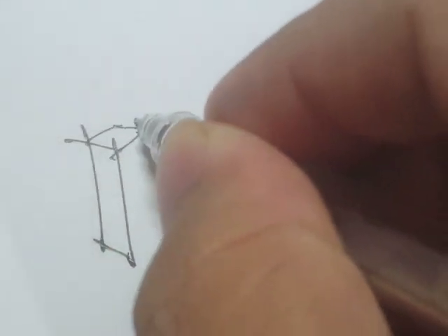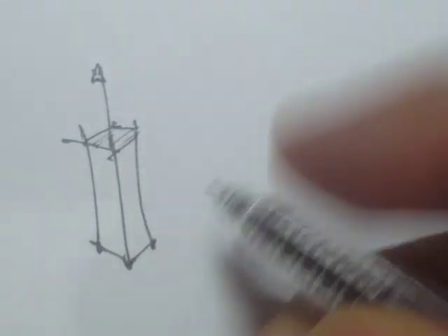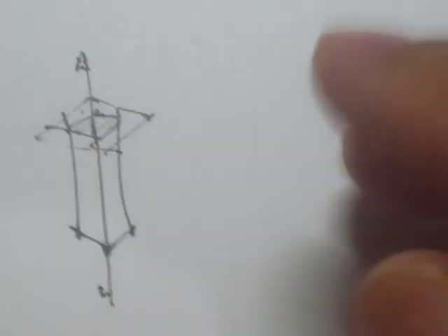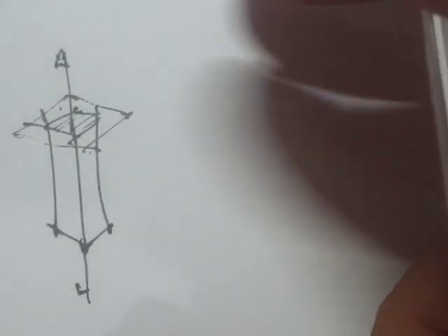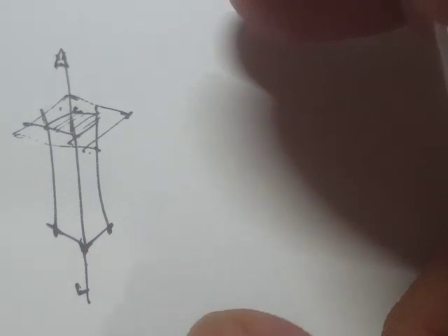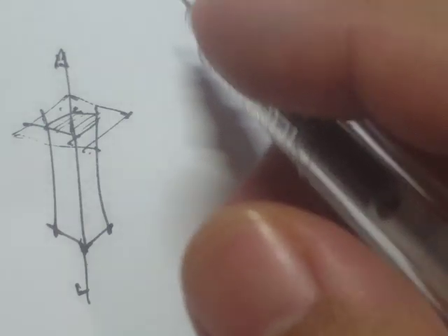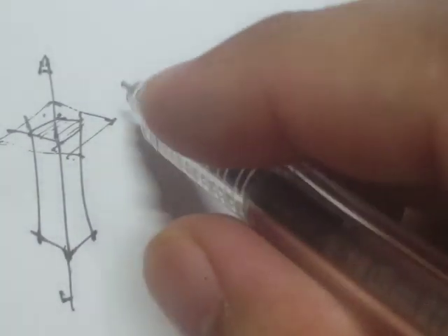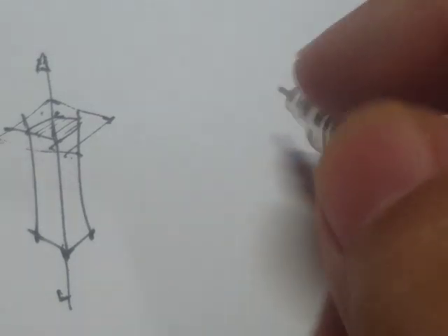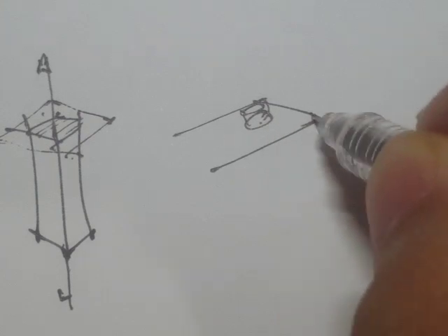Axial loading is a loading that's perpendicular to the cross-sectional area concerned. Typical examples of axial members are columns, struts, some members of trusses, braces, and many more. After this, we discussed members in direct shear. An example of that is bolted connections.